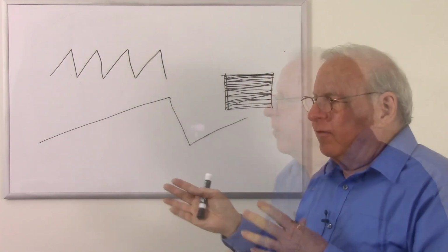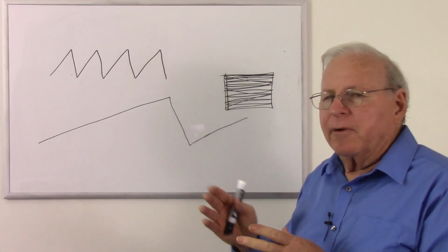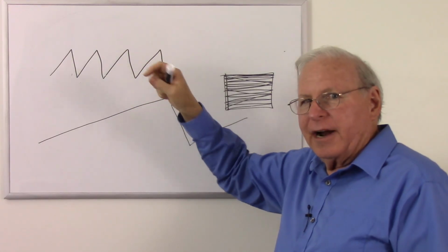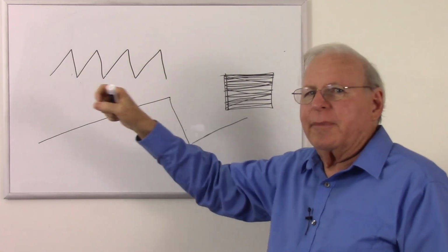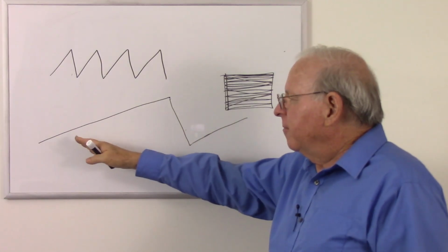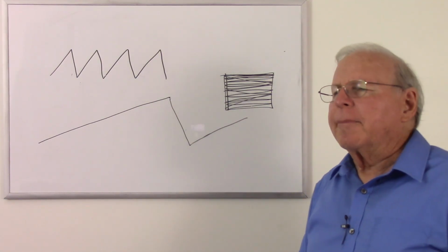So we now have a CRT with magnets to move the beam around. We have these oscillators to tell the beam where to move, that go through amplifiers, to go through the coils of wire to change the magnetic fields, to make the beams go back and forth, and this one to make it go up and down as we've described.